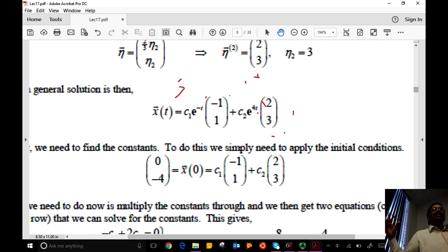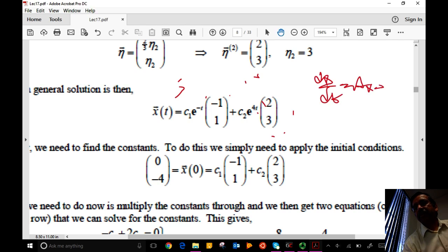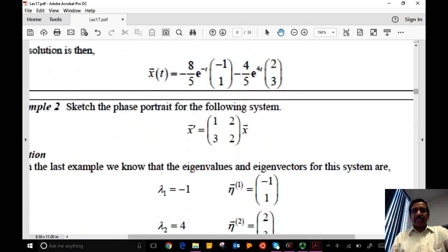That means you want to introduce a control action into the system, dx/dt equals Ax plus Bu. What is u? u is your control action. Okay, so you want to do it in such a way that you move the poles to the left-hand side. You make the system stable through feedback control, for example. Okay, so these concepts mathematically are applicable in a number of different areas, from process control, from hydrodynamic stability theory, nonlinear chaotic dynamics, etc. They're all related. Any questions?